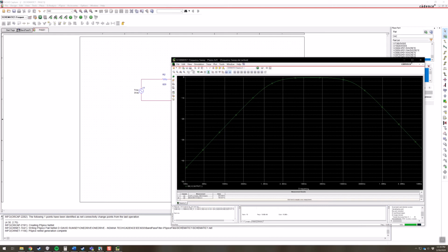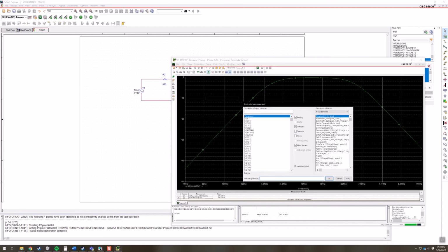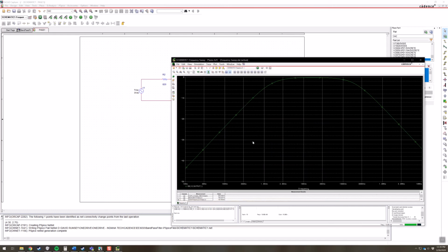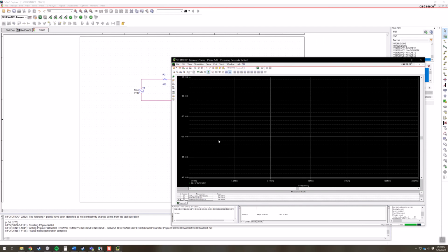Yeah, so you don't put the negative in. Let's go and do this again for the center frequency. So the output, comma, 3. Oh, the comma's already there. And it says the center frequency is 100 kilohertz, which is not at all what our center is. It must not be using the same formula, so we're going to have to look at that for a second. There's something wrong going on with its center frequency computation. But we can still evaluate these measurements.